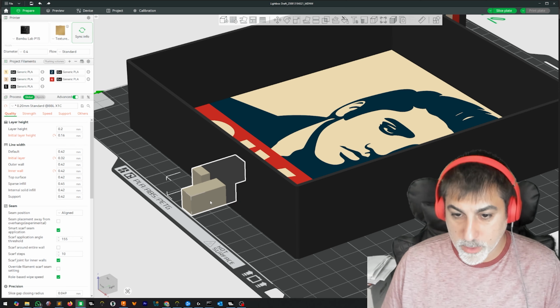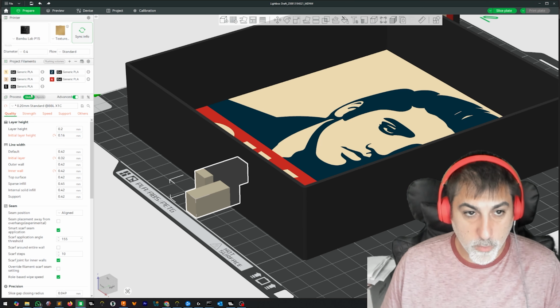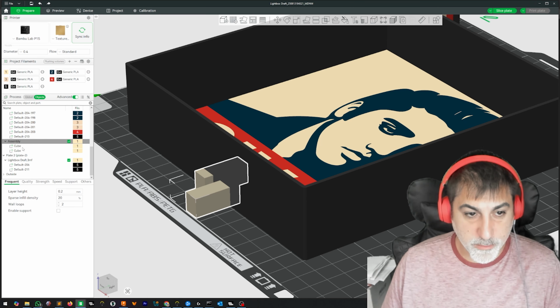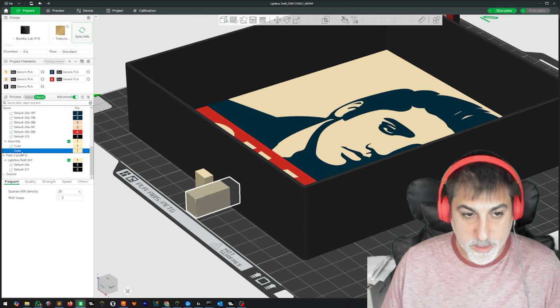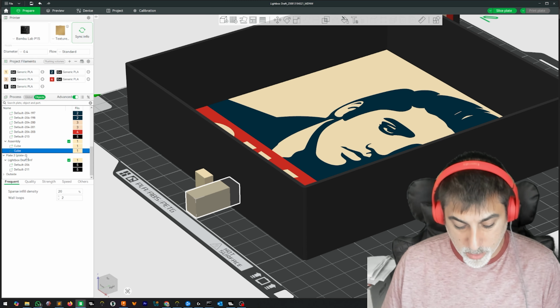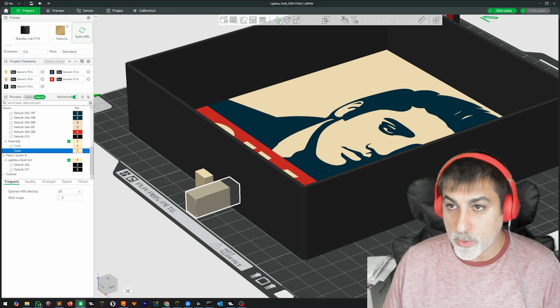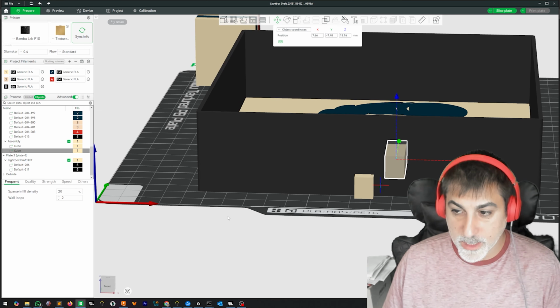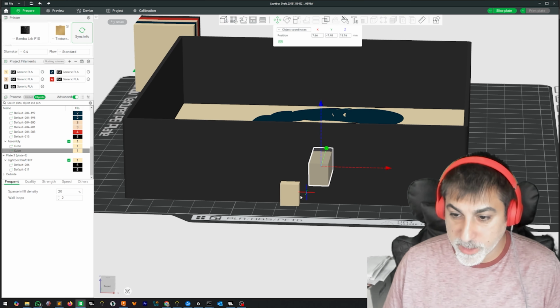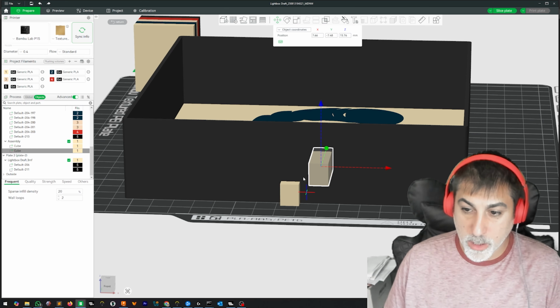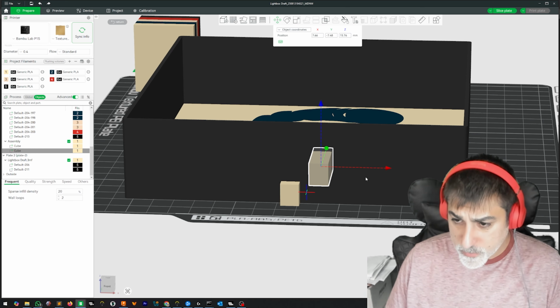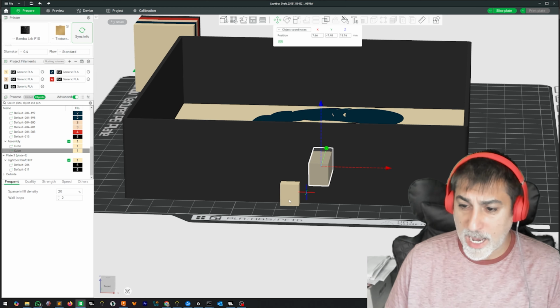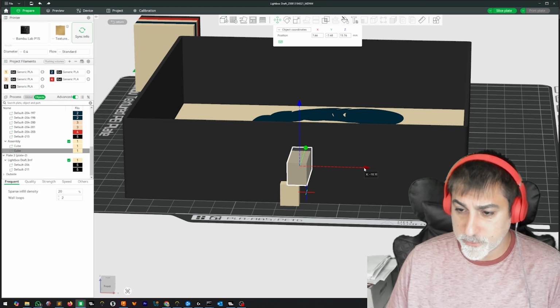Now that they're merged, we want to go to Objects and Assembly, select just our 1 cube, and move just that 1 cube. Now we see that it allows us to float it because it is part of this other cube. They're grouped together in assembly. So that's the lowest part of the object, and this one can free float.